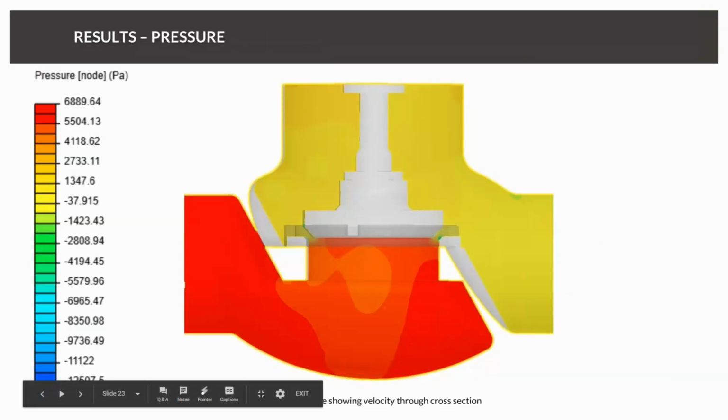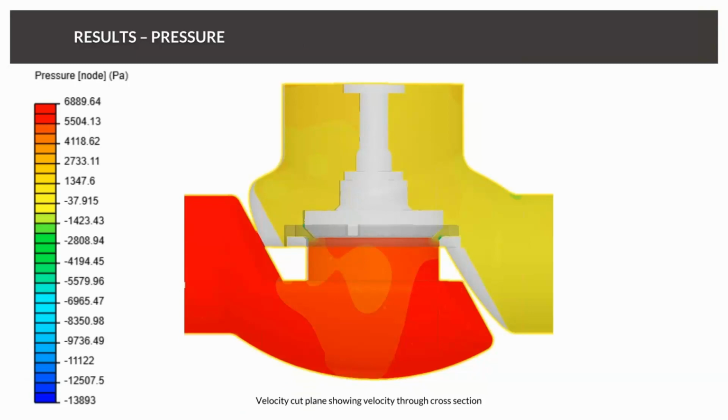All right, so here's pressure, and I think I scaled it just to get something that kind of zeroed in. So all you have to do is just double click and reset the magnitude. If there's one node that has a super high or super low pressure, it can kind of distort the results. But yeah, 6,000, whatever, 800 pascals, that's right about an inch of water, just like our boundary condition. And then you see 0 on the outlet side.